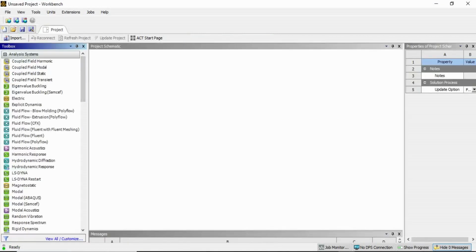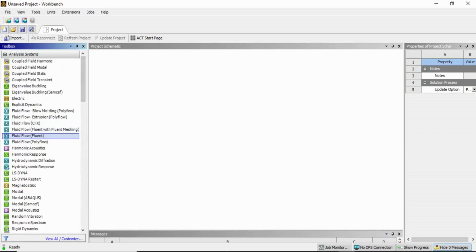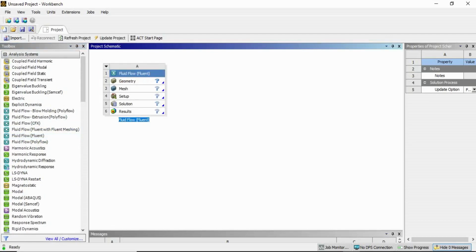ከነዛ አንዱን ሰሌክት አድርጎ ፕሮጀክት ሌአውት በስኬማቲክ ላይ ማዘጋጀት እንችላለን። To start with, drag any analyzing system from the toolbox to project schematic. For example, I will add fluid flow fluent from the analysis system to project schematic. Each cell of the system will correspond to a step in the process of performing the fluid flow fluent analysis. ስለዚህም እኔ ምን አድርጌያለሁ? አናላይሲስ ሲስተም ላይ ሄጄ fluid flow fluent የሚለውን drag and drop ወደ project schematic አድርጌያለሁ። You can rename your system as you can see to specify a unique name. For example, I will rename it to CFD Fluent 1.